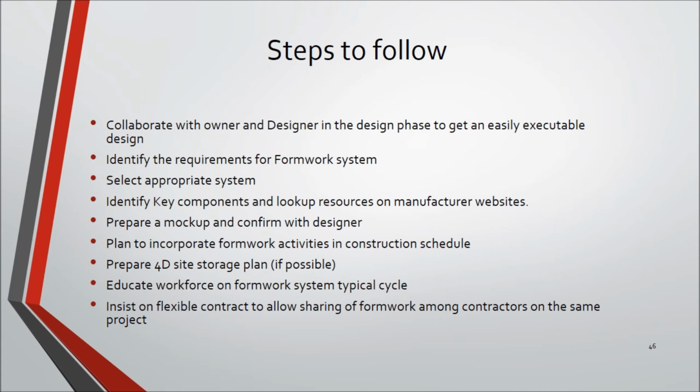Fourth, identify key components and look up resources on manufacturer websites. I have provided a list of websites at the end of this presentation for reference. Fifth, prepare a mock-up and confirm with designer. Make sure you and the designer are on the same page. Sixth, plan to incorporate formwork activities in construction schedule. Seventh, prepare 4D site storage plan, if possible to show the location of storage of materials in 3D space with time. This will minimize clashes between activities due to storage.